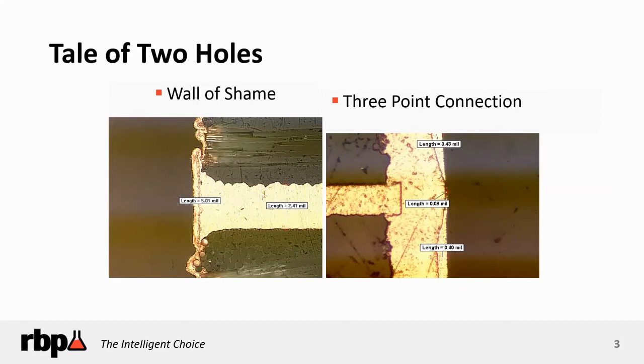Why? Number one, the fabricator had excellent control of his drilling. Number two, the resin and lamination cycles were in proper control. And in addition to that, the drilling was excellent. So was the desmear process, where it did not overpenetrate or cause wedge voiding.